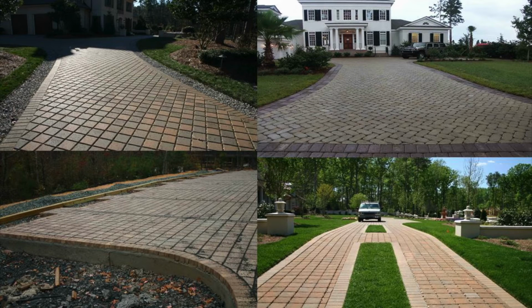Sometimes you'll see the architect or designer will want to have the paver be solid, no curb expressed. So we can recess the curb, mortar or adhere with high strength adhesives, as you see in the lower left-hand corner there, and still be able to give that same effect. So there's ways of doing it. You just need to make sure you're structurally okay, and then figure out the method that will meet your aesthetic requirements.